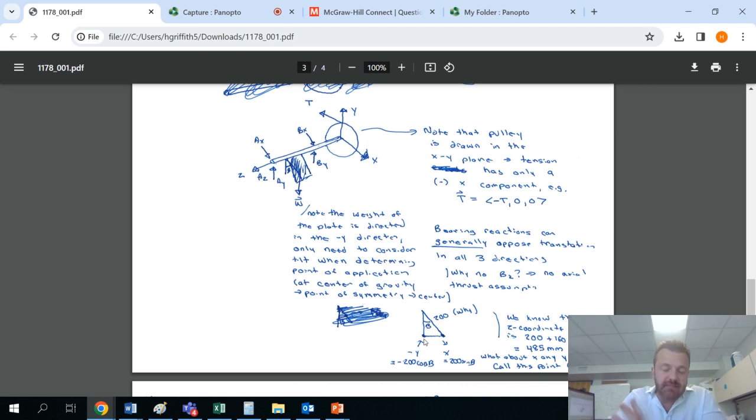And we can determine that, again, by trigonometry. We don't know this base. We don't know this base. However, we know for this hypotenuse that this side length, which corresponds to how far out it is in x, is going to be 200 times sine. A good example that you always want to draw out your triangles and not always assume, well, x is cosine and y is sine. In a similar fashion, the y displacement is going to be 200 times cosine of beta. And remember that that's in the negative direction relative to our coordinate system.